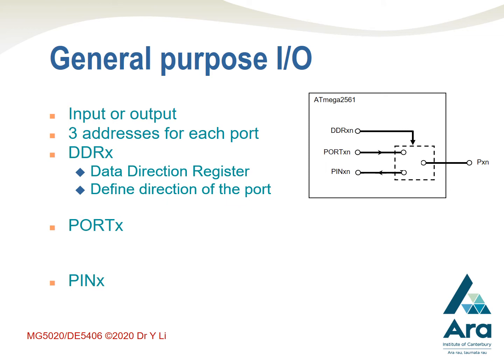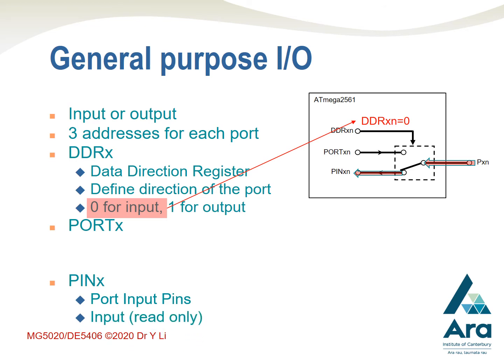DDRX is the data direction register that defines the I/O as input or output. The value 0 defines the pin as input, which, as you can see from this diagram, forces the switch to connect to PINX, so that we can read the external signal at the pin from PINX. So PINX is for us to read the data appearing at the external pin.